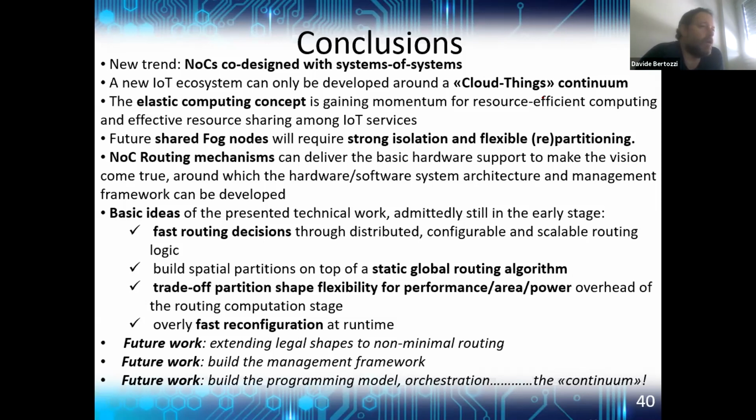This is typically called a virtual infrastructure, virtual fabric, a virtual computation and communication fabric built on top of an FPGA fabric. I think that you could use the FPGA for more invasive reconfigurations, while for this kind of fine-grained configurations a dedicated solution is the best way to go.